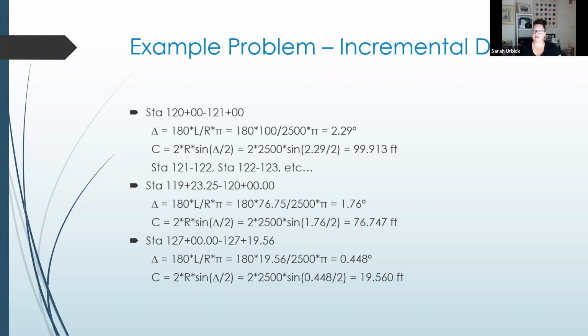So the key to that, horizontal curves are circular. I've said it 3 or 4 times now. It would behoove you to write that down. That's what allows us to use these formulas, to have this standard and to say we're going to break this into manageable chunks. The unmanageable chunks, those 2 little funky end caps or end pieces, are partial stationing.